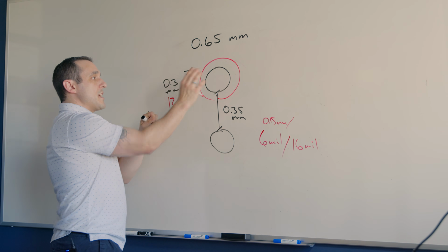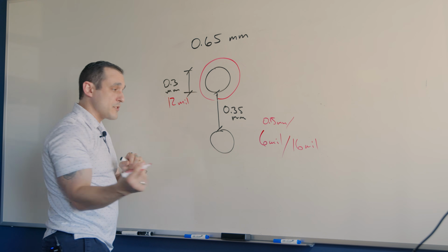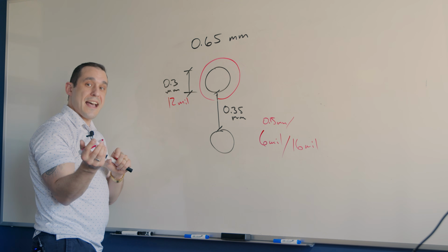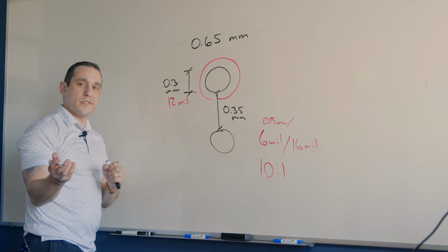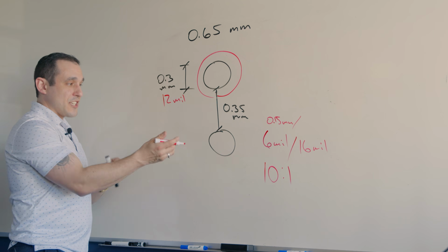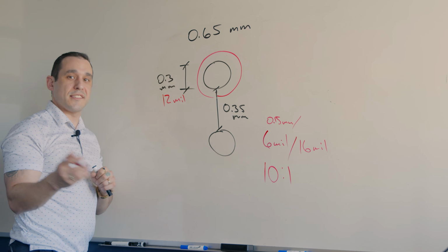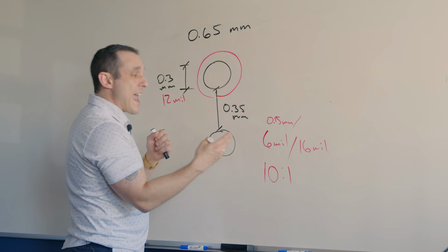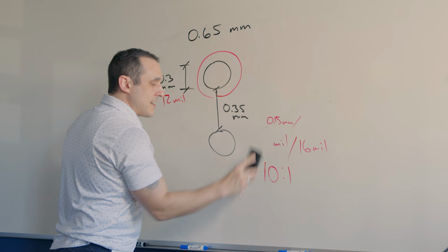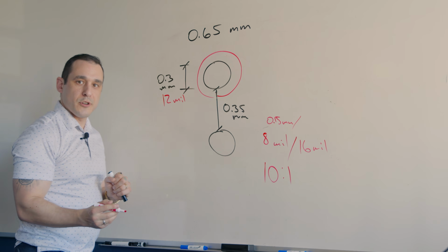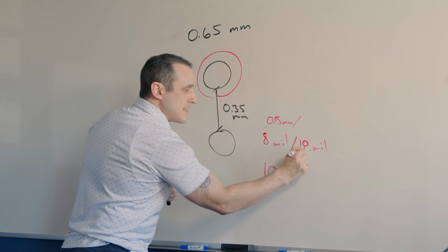Now this 6 mil drill in this pad may not actually be practical at all, because if you have a standard thickness board and you're trying to do a through-hole via at 6 mils, that's going to require a 10:1 aspect ratio on those holes. That 10:1 aspect ratio at a 6 mil drill is usually larger than what a lot of fabricators will guarantee in their processing capabilities. Typically, they'll only allow an 8:1 aspect ratio with a 6 mil drill. So that might force you to instead use an 8 mil drill diameter. And if they require a 10 mil pad oversize, then that sets your pad size to 18 mil.